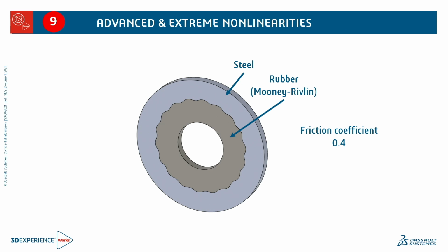But if you look at any friction chart, 0.1 is a pretty slippery surface. So here we've got 0.4 in this particular model. And what we want to do is rotate that rubber shaft by 1 notch, and then look at what is the moment that we are dealing with in order to progress through that.